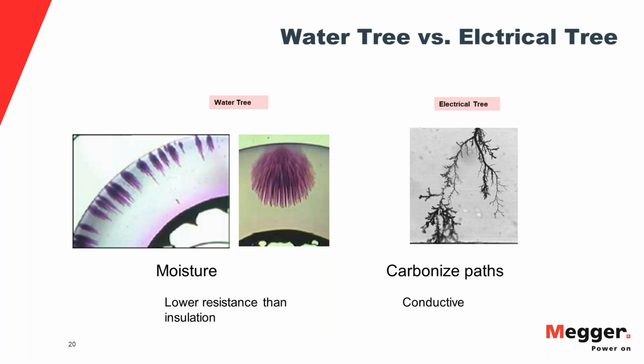And then again, a comparison of the water tree: you have different types. You have the typical vented tree, like on the left. In this case, by the way, it's an almost uniformly aged cable, so that's not really critical. While the picture on the right there, this big single water tree, that is a real critical water tree.